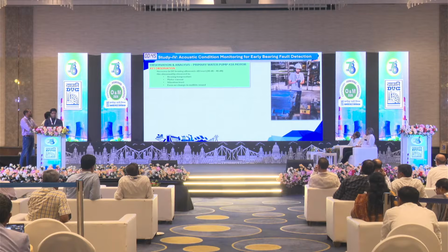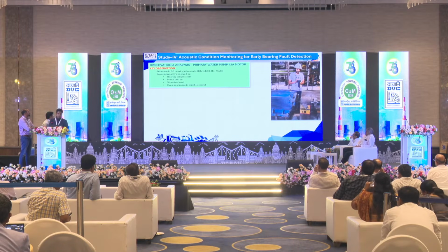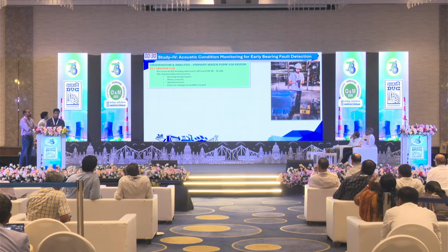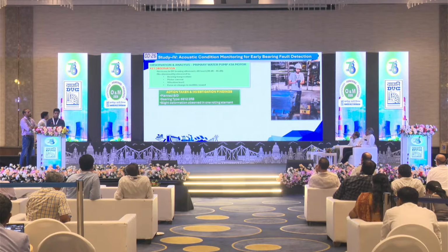After implementation of this practice, within 2 to 3 months, we got the result. During routine checkup of primary water pump 2A, we found a dB level rise from 30 to 46 dB, although there was no other abnormality in terms of bearing temperature or any abnormal sound in audible range. So we took a shutdown of the motor, changed the bearing, and also made the drive available. When we analyzed the replaced bearing, we found a deformation in one of the balls.